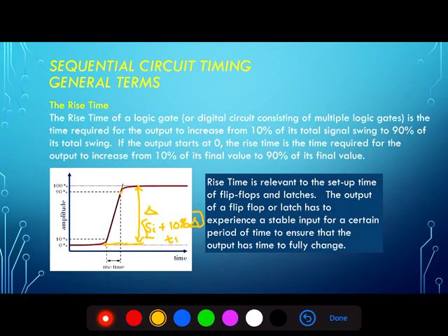And in the rise time, the other time that we look at is the time required for the signal to reach 90% of its final value, or its initial value plus 90% of delta, or the whole range. The time associated with that value is called T2, and then the rise time is just T2 minus T1, which is typically in nanoseconds or sub-nanoseconds for digital circuits.